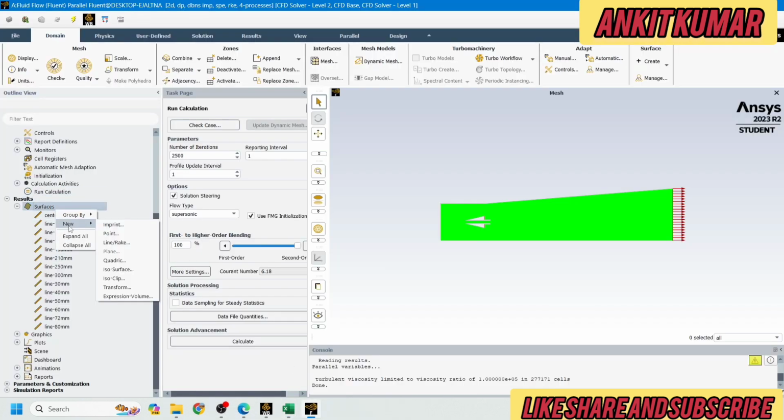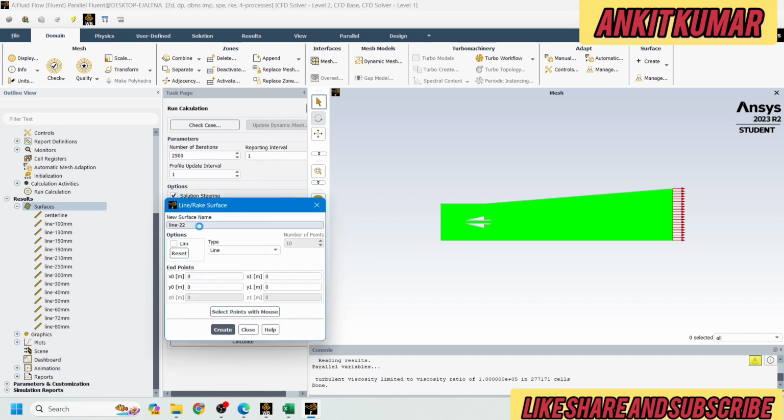I'll create one line at 50 mm. Click on new, right click on the surface, go to new, go to line and rake, then write the 50 mm line I am making. So 50 mm in meters, how much will it be? 0.05, and the y value we will write from -1 to 1. I'm writing -1 to 1 because it will cover the full range.